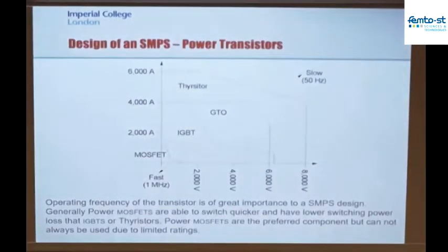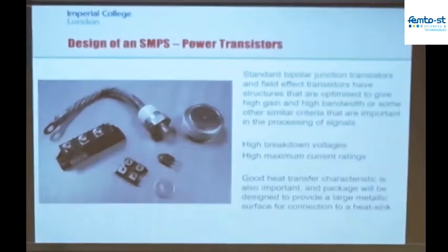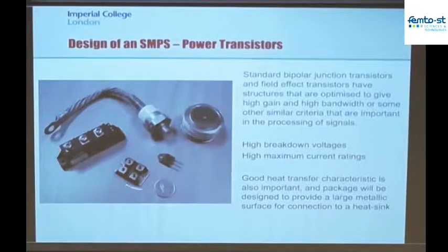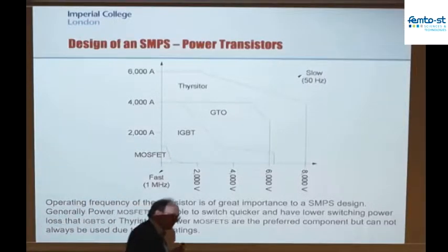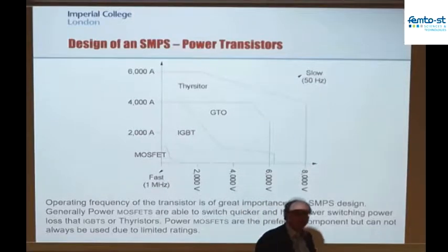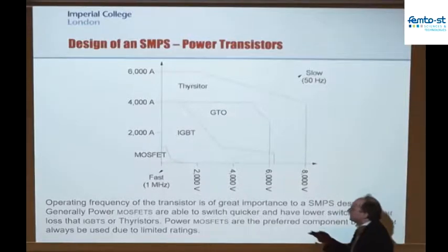Okay, so the components. I already showed you this picture earlier of a bunch of different power semiconductor devices. So transistors, diodes, etc. In this case, that are designed for handling energy rather than for processing information. We're really going to be concerned here with using MOSFETs. At this sort of power processing level for energy harvesting, almost certainly you will be using MOSFETs. Never use a BJT, bipolar transistor, in power electronics. It's almost always a bad move compared to using a MOSFET.